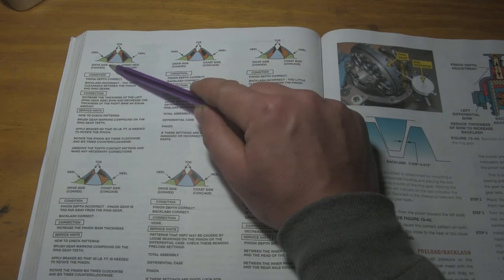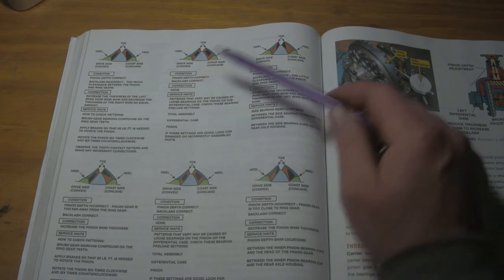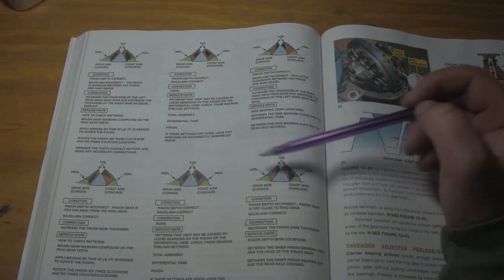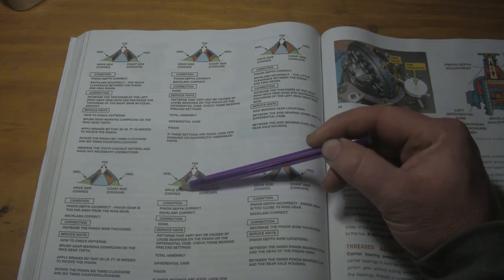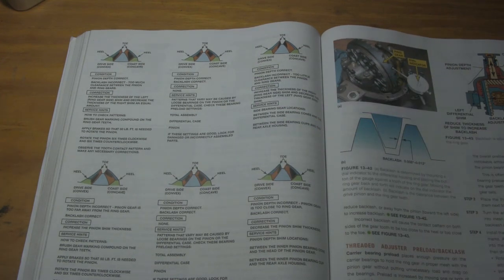So the contact pattern between the heel and the toe has to be correct. You can't be too far off on an edge. You can't be too tight into the middle. You have to be kind of like right here, right in the center portion of the gear. You want to be about 50% in the middle and 50% up and down. And one of the only ways to really adjust that gear contact pattern is by moving the pinion gear inboard, like changing shims and dropping the pinion gear deeper or shallower into the case. And then you can also set the ring gear left to right with shim packs.